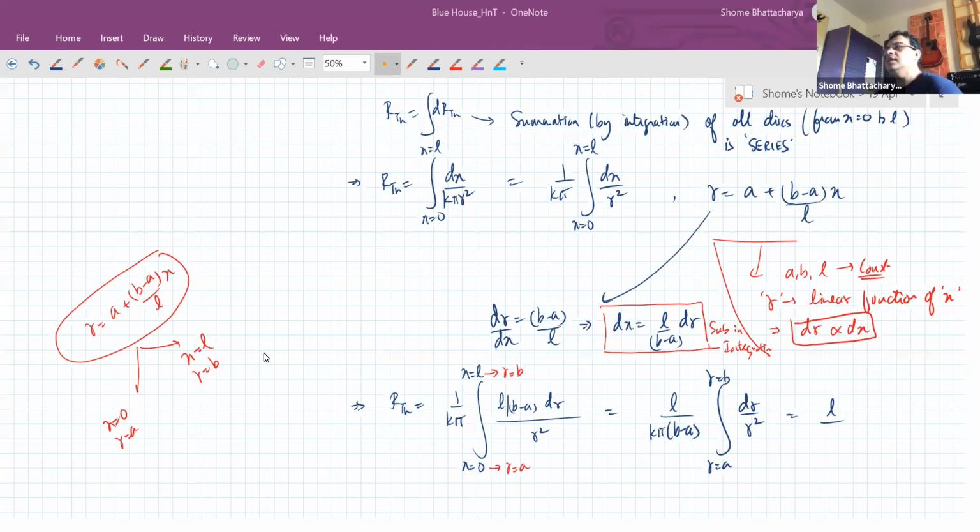See, it is not like we are integrating for a moment of inertia or something like that. In that case, if we were dividing it into dm elements, you can see it is actually a volume distribution of mass. But that applies when we are doing some kind of integration for mass, like for center of mass, where we do integration of x dm divided by total dm, or for moment of inertia, that is dm into r square or whatever. Then we think whether it is a surface, volume or length distribution. But in this case, only a line integral is considered, not the volumetric integral or the areal integral.